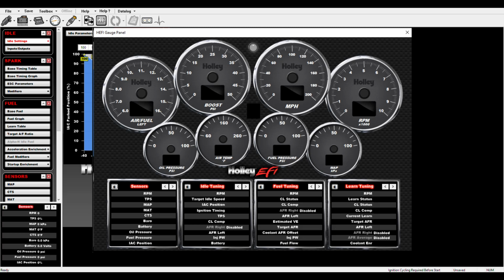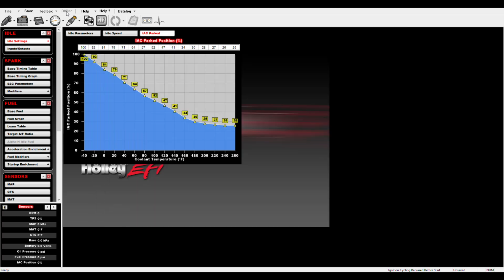And probably the last big thing that everybody always tells you when you go on the Holley forums, if you can't get your car to start, the first question is, did you do a throttle setting procedure? The ECU has to learn what the various throttle positions are. So you start with it closed at 0, you follow its instructions, you ramp it all the way to fully open, then fully closed, then fully open and fully closed, and it essentially learns the voltages all the way through that range so that it can calibrate your TPS. So that's the gist of it.